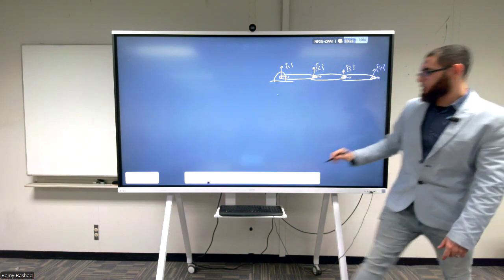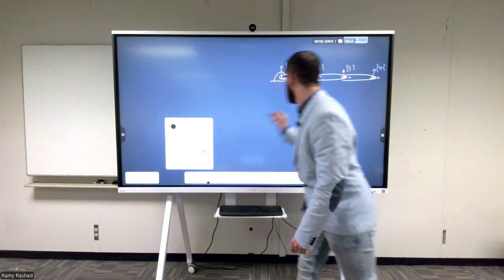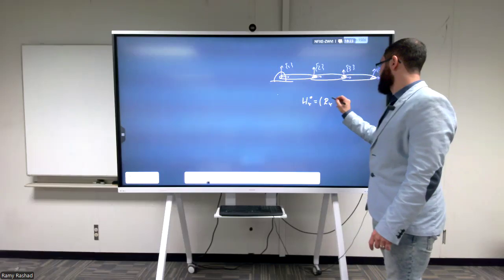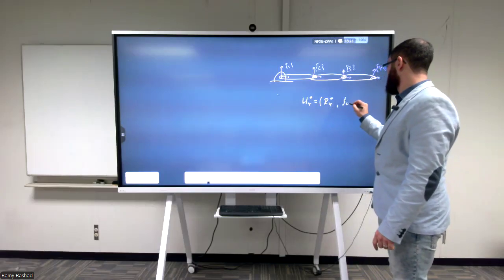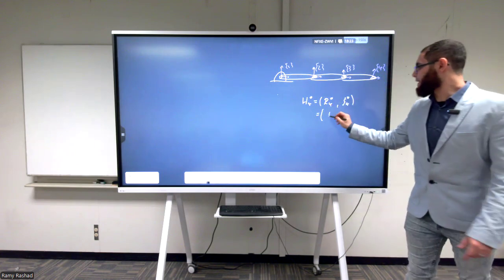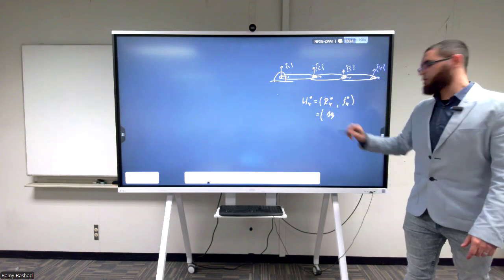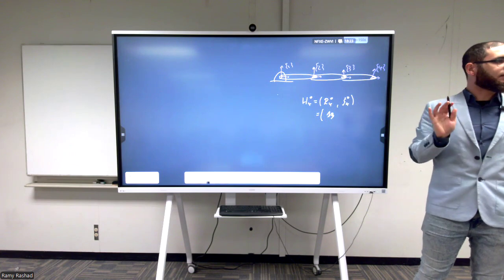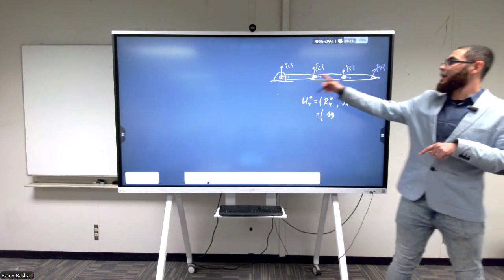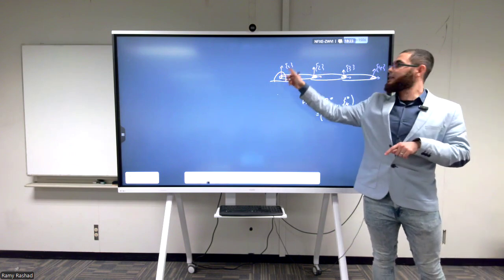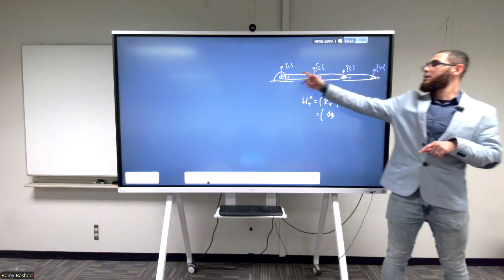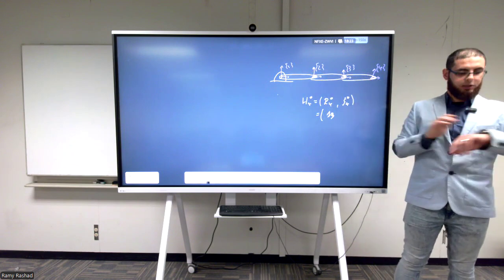What is the h of 4 with respect to 0? It's a pair of r4 with respect to 0 and psi of 4 with respect to 0. What is r4 with respect to 0? Identity in 3 dimensions. It's a 3 by 3 identity matrix, because I chose, and again, this is a choice, that the reference frame here is identical to the 1 frame. So this is the 0 frame, and you see here, they have the same orientation. I'm doing it by inspection.